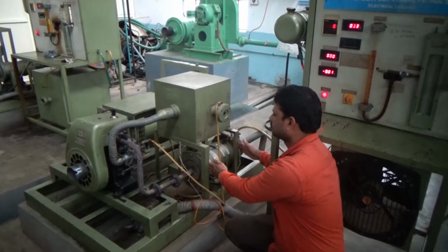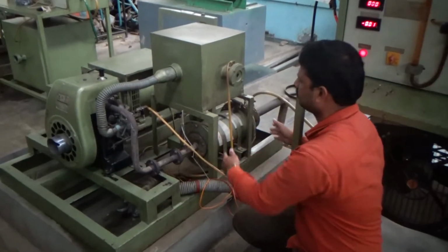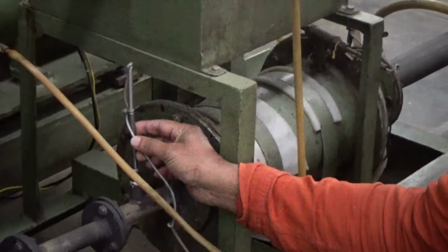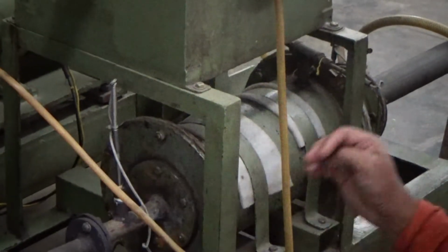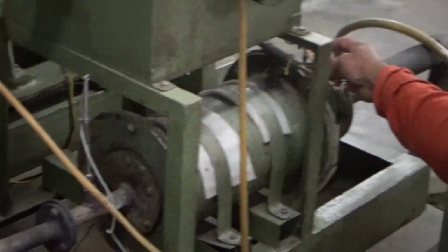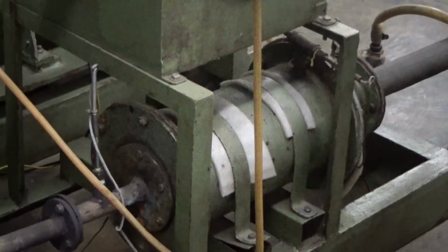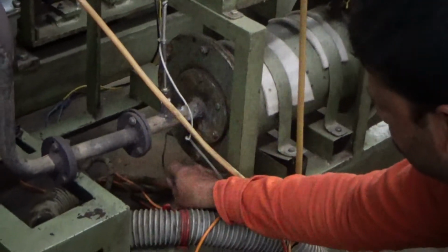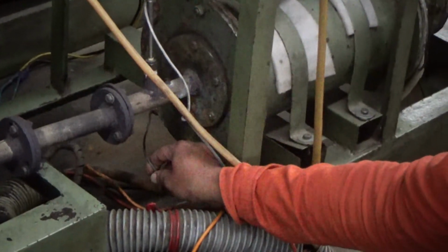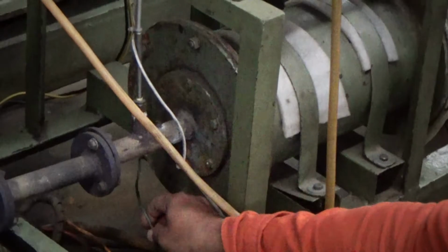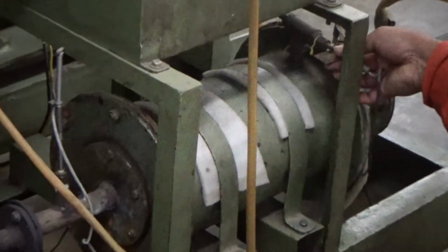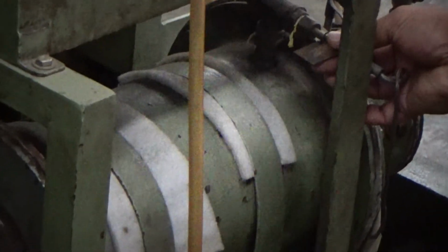So this is the calorimeter. We have an exhaust gas inlet for the calorimeter, and that's the T1 temperature sensor, before the calorimeter. Following that we have another temperature sensor after the calorimeter, that is temperature T2. Then we have the water inlet temperature T3 and the water outlet temperature T4, which is being used for cooling purposes.